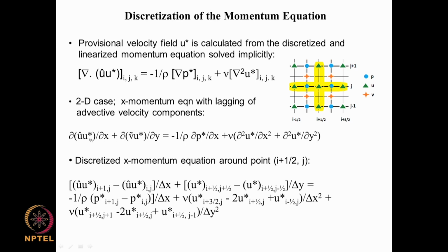Now, if you come to this term here, again there are two velocities. It happens to be the same here, but within this the coefficient velocity at this point is taken to be the average of these two. When this term needs to be evaluated at this point, the coefficient velocity is taken to be the average of these two, and the u star, which is the equivalent of phi, is done using upwinding.